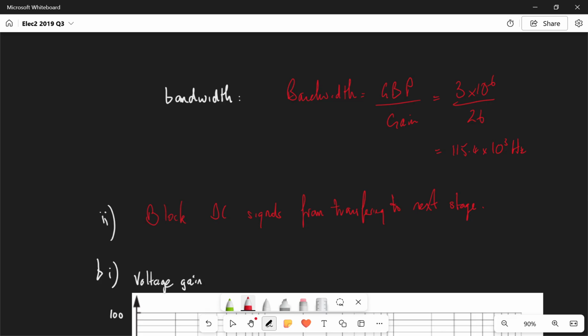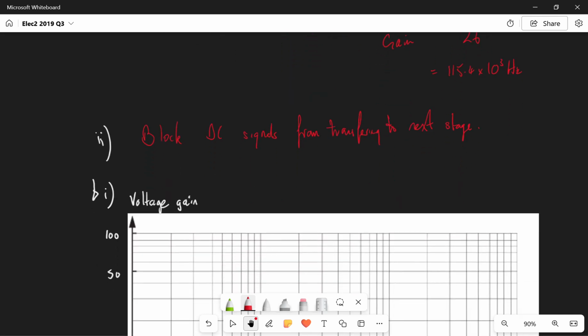What you can think of them as is passive high-pass filters, and so they block low frequencies. And if you think between those capacitors and the 0-volt rail is an infinitely high resistance, then their ability is very, very good at blocking very, very low frequencies.